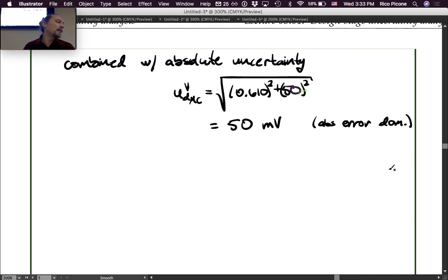And that's coming from the fact that each of these analog inputs, 50 millivolts isn't an insignificant amount of voltage. It's difficult for them to guarantee you, when they ship all these things, that you're going to be more accurate than 50 millivolts. They try to calibrate them as well as they can and manufacture them as well as they can to be within that, but that's all as good as they are. So these things aren't great for high precision voltage measurements.